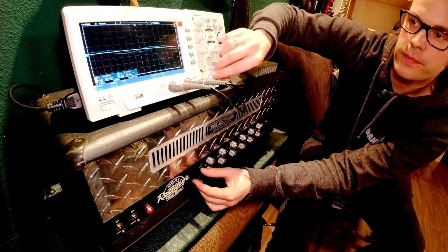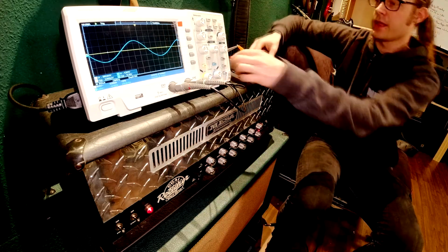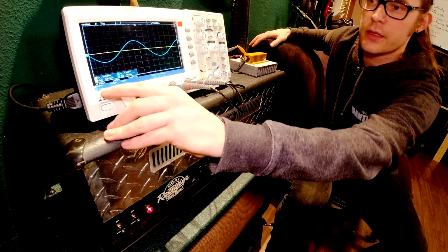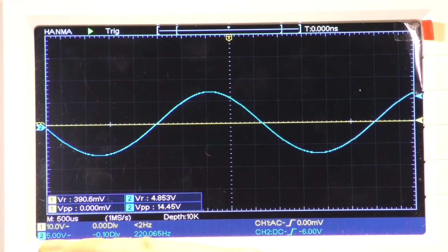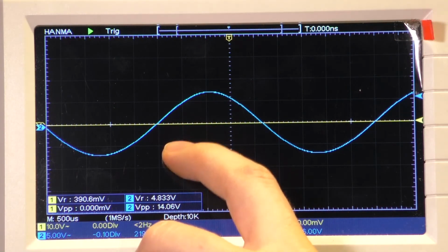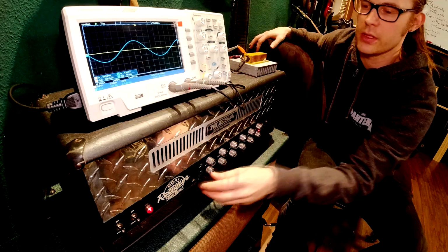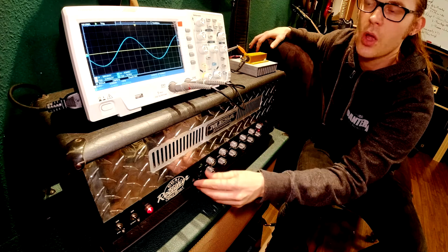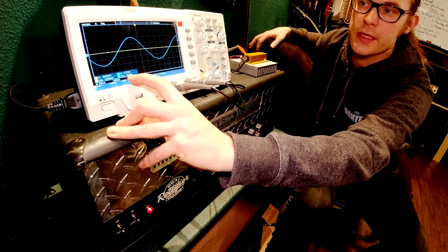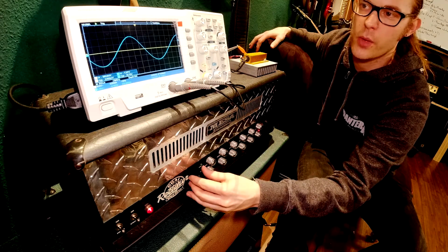and we can see, make it a bit better here, there is a sine wave on this resistor right now, and here is the division, 5 volts per division, so each step is representing 5 volts. So if we take this, we have a peak to peak of 20 volts, and we can see it down here, nearly 20 volts, pushing a bit higher though, there we go.